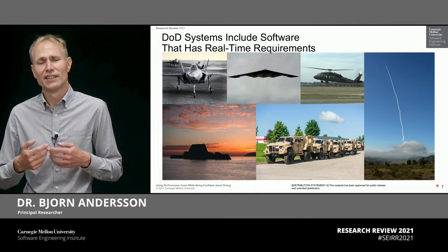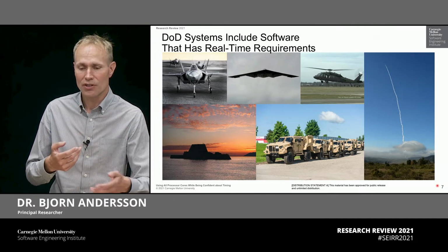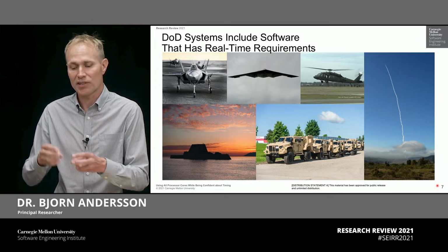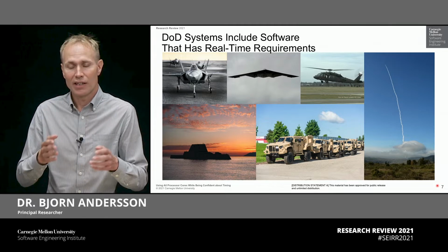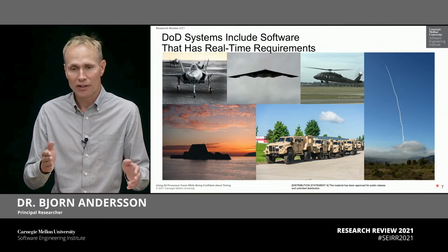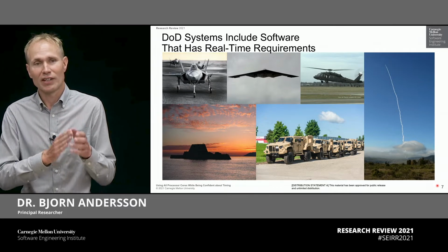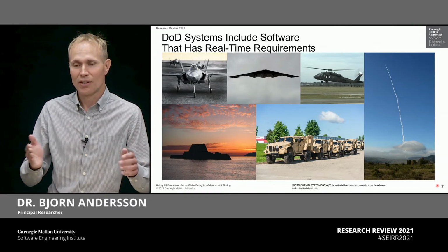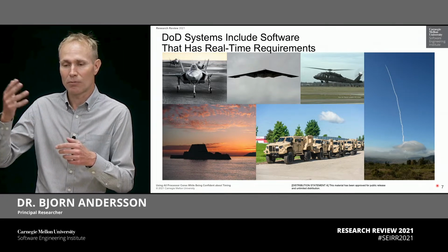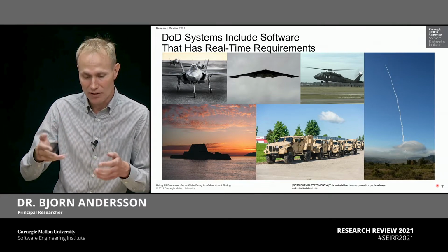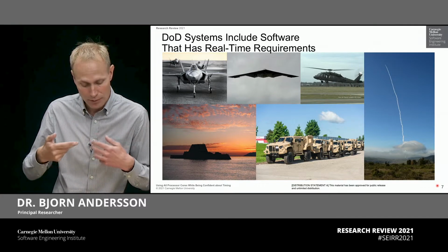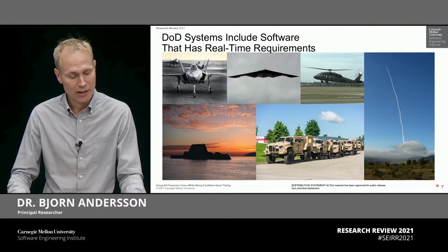You can ask, why is that? It is because the software reads sensors, and before it commands, it performs computations based on those sensor readings to decide what the actuation command should be. And if the software is too slow, if the delay from sensing to actuation is too large, then the actuation is based on old information. It's old news, and then you're acting on old news. That can cause instability in control loops, but it can also cause other bad effects, like a countermeasure not being deployed at the right time. You may compute the right result, but it's computed at the wrong time, so therefore the interaction is bad. For example, the countermeasure is deployed at the wrong time.